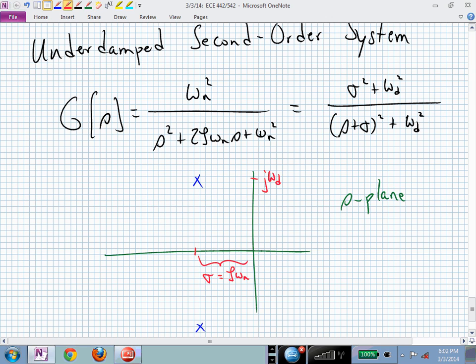And that damped frequency, that's damped, with a P on there, omega sub d, is related to the natural frequency, omega sub n, by this damping amount, square root of 1 minus zeta squared.